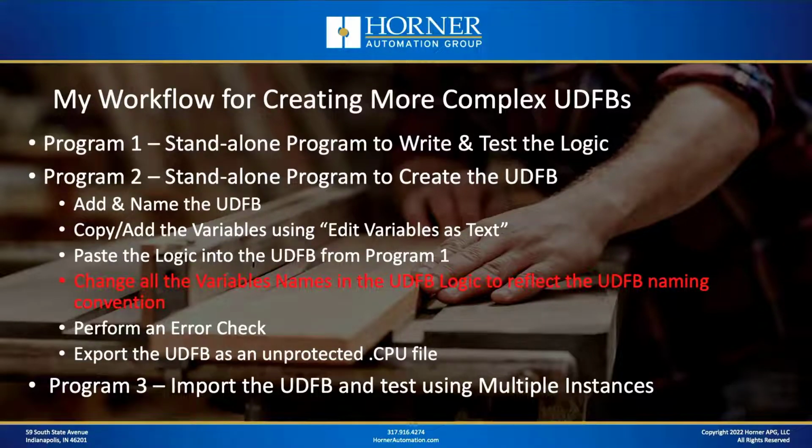Start with a brand new program, and I create a standalone program that contains the logic that ultimately is going to be the UDFB. And then I not only write that logic, of course, but I thoroughly test it. Once I'm done with that and I'm satisfied with the way things work, then I create a brand new Cscape program or project, the purpose of this new project is going to be for the creation of the UDFB itself.